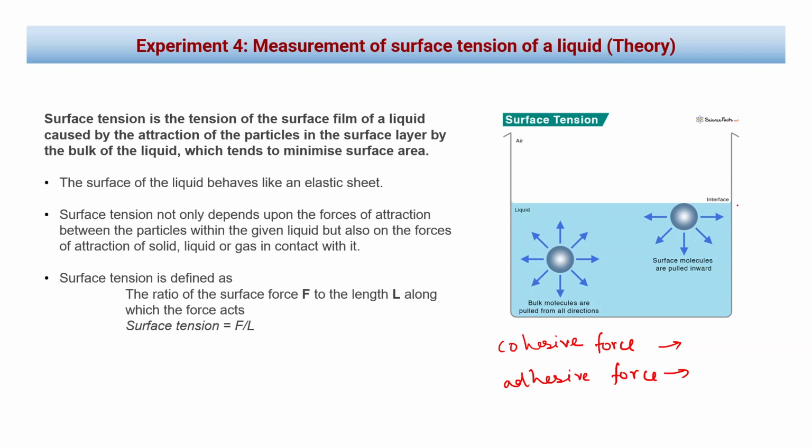But they are different kinds of molecules, different material, so the force acting between them will come under adhesive force. So the force on one molecule because of the other molecules, which is pulling this particular molecule in all directions, is the origin of this force called surface tension.